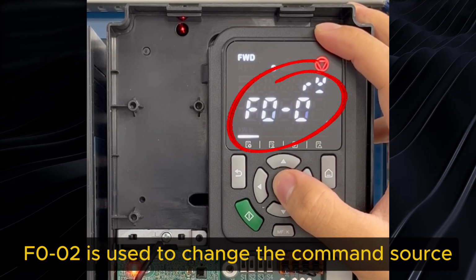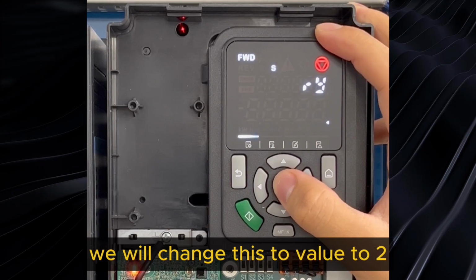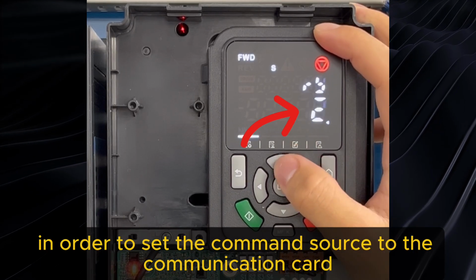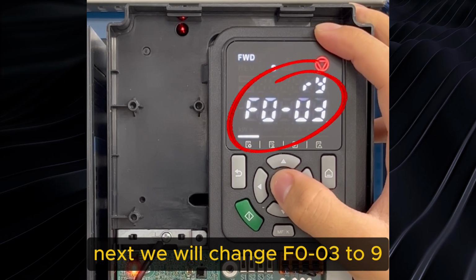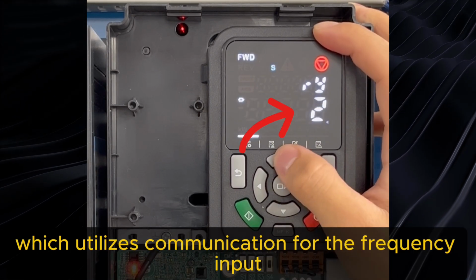F0-02 is used to change the command source. We will change this value to 2 in order to set the command source to the communication card. Next, we will change F0-03 to 9, which utilizes communication for the frequency input.